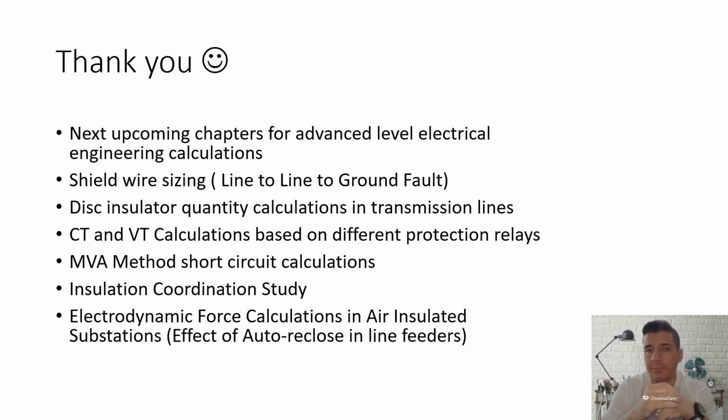And if you are working in a company, I would suggest you use PLS-CADD Lite. It's a very light and very easy version to use. But even together with that one, I will give you an Excel tool also. In that Excel tool, you will see what the total length of the conductor is, what the required sag in that conductor is, and what our limitations are in one transmission line, where to put one tension tower and the other, suspension tower. So what are those limitations? These are like temperature, ground level, I mean inclined spans, most of them. Okay, I will try to explain one by one.